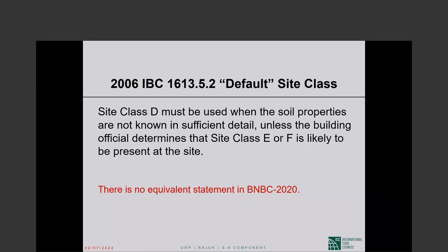Okay. So site class is based on measured properties of the soil at the site over the top 30 meters or so of the site. The preferred property to be measured is shear wave velocity. If that cannot be measured, then we can go with either the standard penetration resistance or blow count or undrained shear strength.